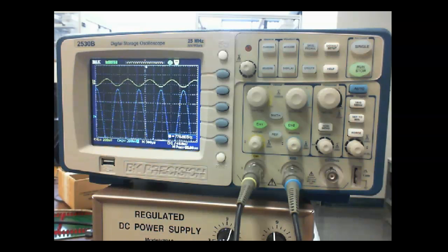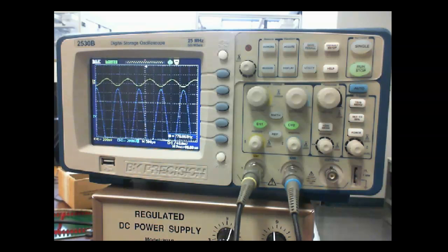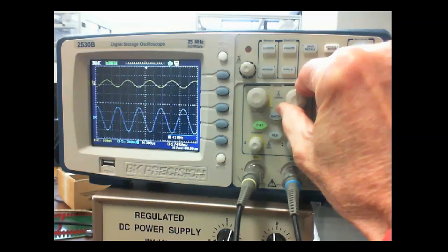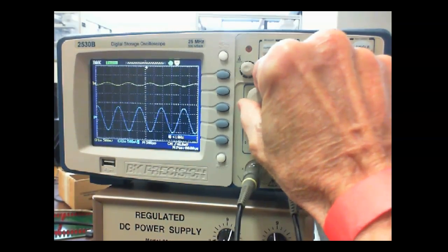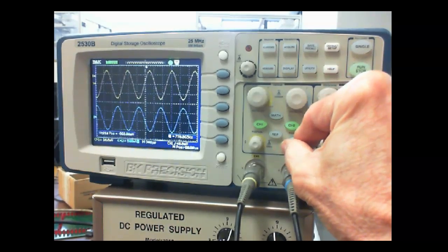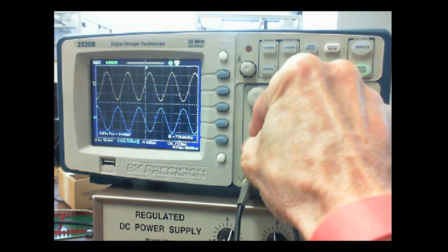Technically we can calculate the gain right now, just taking the collector and dividing it by the emitter. Okay, but mine's a little low, and we'll explain that in a minute. Mine's loaded. That is the unloaded gain. So the unloaded gain is RC divided by RE. The blue is mine. If it was unloaded, I should expect a gain of 10, but we're going to see it's going to be less because mine's actually loaded.